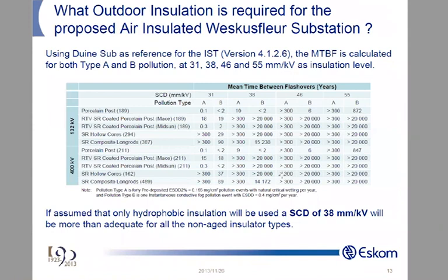Right, sir? These RTV coatings, how long do they last? Well, we've got more than 20 years' experience with coatings locally. I've evaluated most of them in relation to one another. There are very poor coatings, terrible ones. I've got ones that have flashed over 4 times in 1 year in my test station. I've got other ones that haven't flashed over to date. So yes, they work, and no, they don't work. It depends on the coating.